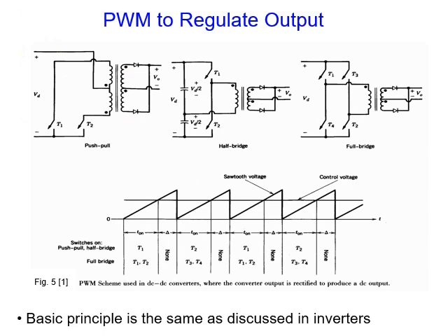Okay, let me start. Just to remind you also, everything is to be controlled using pulse width modulation. Now you remember these two switches in the push-pull here. This is push-pull, if you remember the inverter. And this is the rectifier, two diodes, as you can see here, a center tap transformer, and the load connected here.